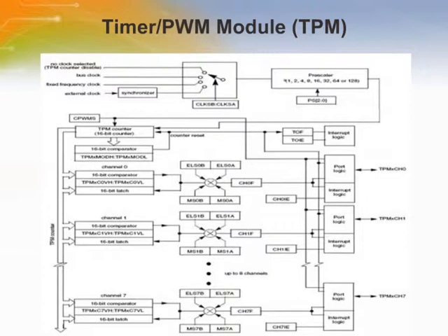The timer counter modulo registers, TPM mod H and TPM mod L, control the modulo value of the counter. The values 0 or FFFF effectively make the counter free running. Software can read the counter value at any time without affecting the counting sequence. Any write to either half of the TPM counter resets the counter, regardless of the data value written.